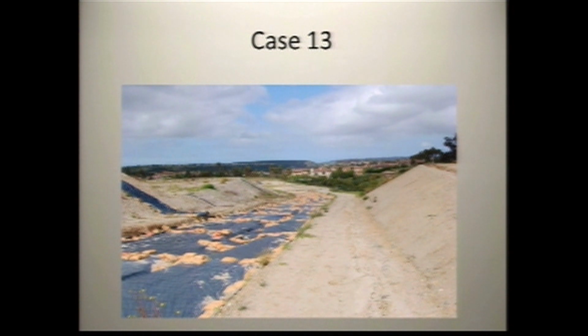This is a cul-de-sac, the downhill cul-de-sac, and there's an inlet down there. A huge amount of sediment came out onto the golf course. Well, I can tell you exactly how much came out onto the golf course. It's about 5 feet wide and 6 inches deep and about 400 feet long. That's the volume of sediment, and it was just excavated under that visqueen. So something like this is evidence of pollution leaving the site. And they got to pull up the visqueen, redo the street, and do something else.